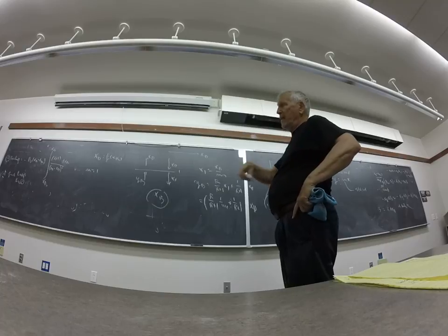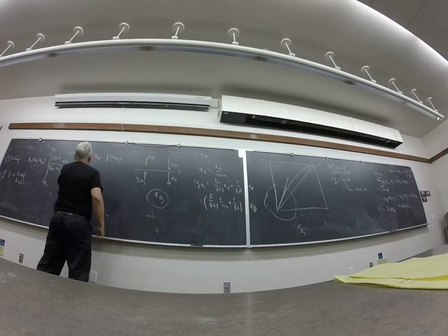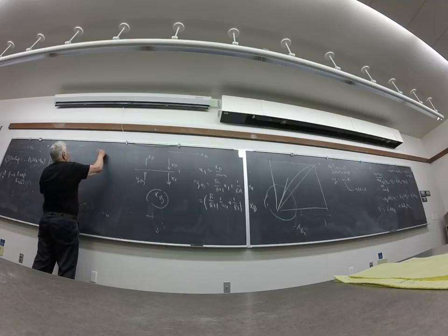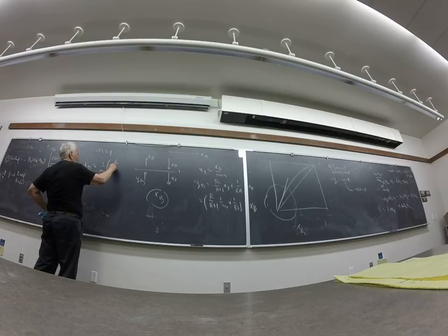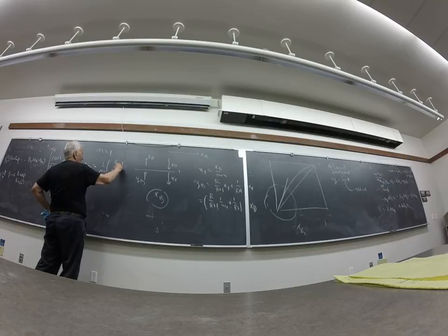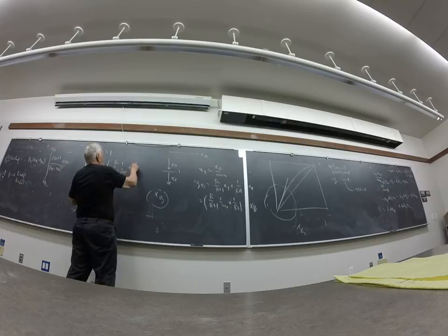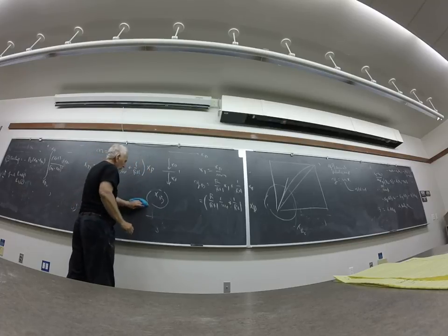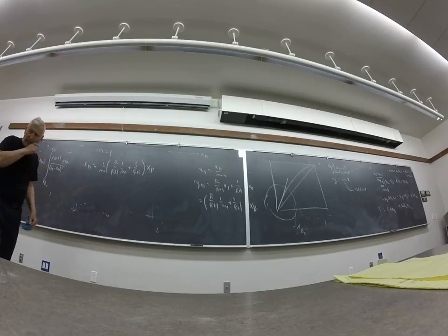Now, xb is yb over m, so I have my first result. For n equal to 1, I'm going to write xb is 1 over m, r over r plus 1, 1 over m, 1 over r plus 1, xd. This is how xd and xb go together.